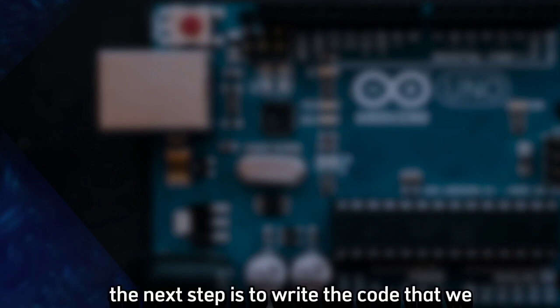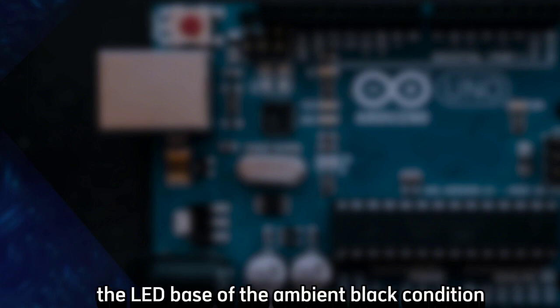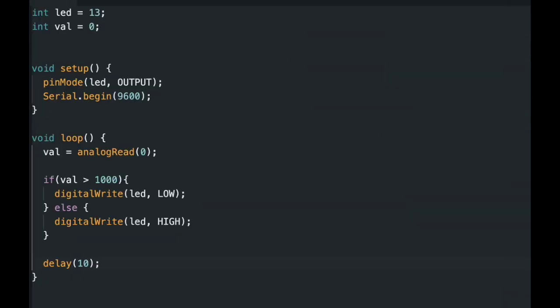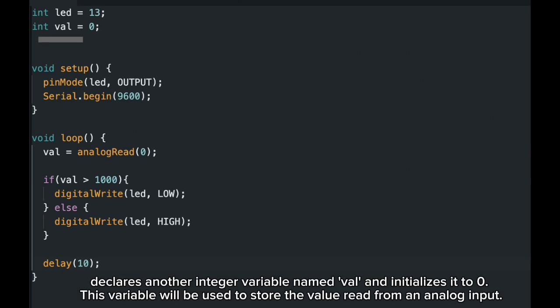The next step is to write the code that will allow your Arduino to automatically control the LED based on the ambient light condition. We will discuss this code one by one. This line declares an integer variable named LED and initializes it to 13. This variable will be used to represent the digital pin number, usually pin 13, where an LED is connected. The next line declares another integer variable named val and initializes it to 0. This variable will be used to store the value read from an analog input.